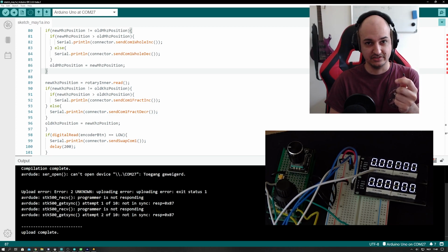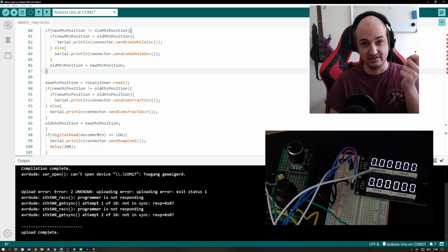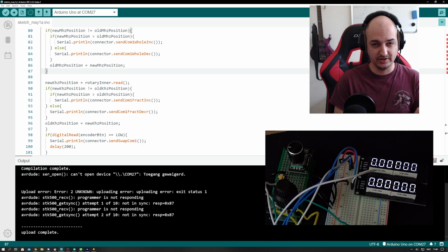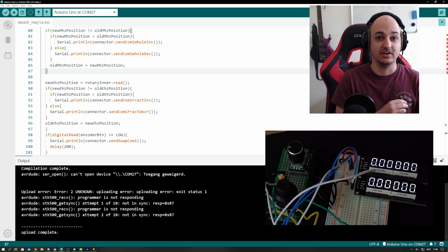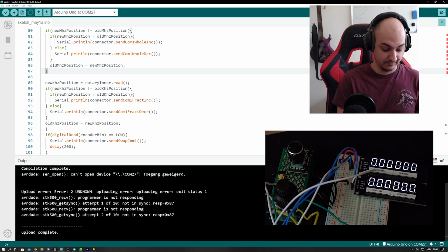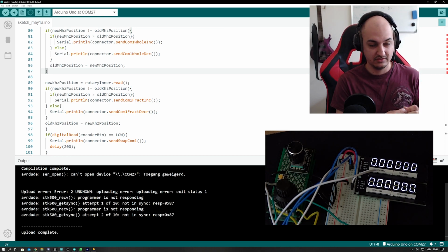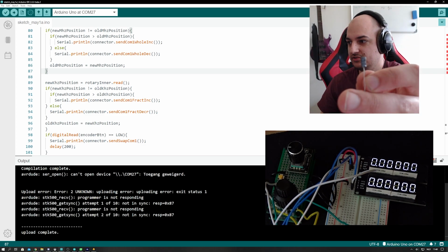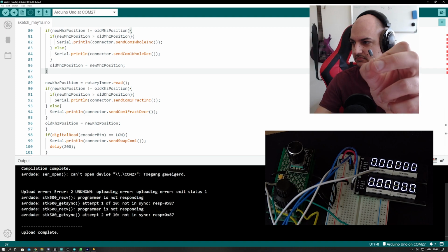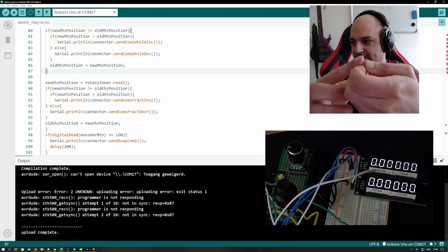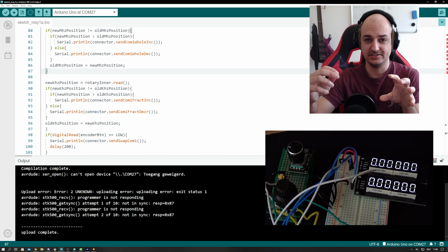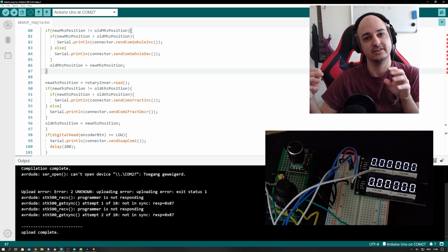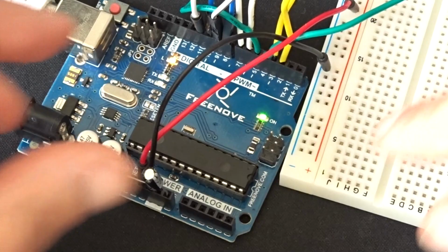Okay, whatever. If you use a Uno, Nano, Mega, or any other one of those chips, we're going to need a capacitor. I've been using a 4.7 uF one. A 10 uF will work as well. You need it to make sure that the board doesn't reset every time it receives data over serial. Now we're going to place it between ground and reset. It has a side that's black and a side that's white with dashes. The dashes are the ground side and the other one goes to the reset.